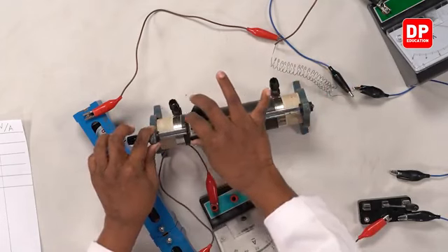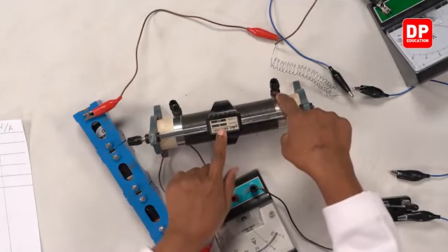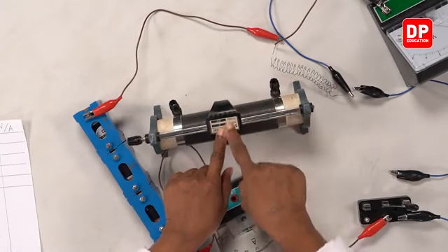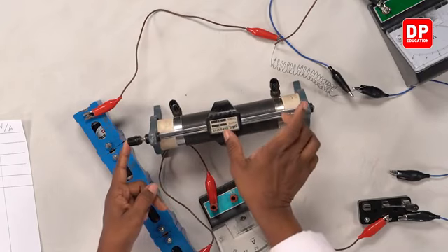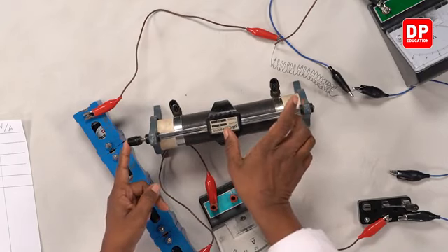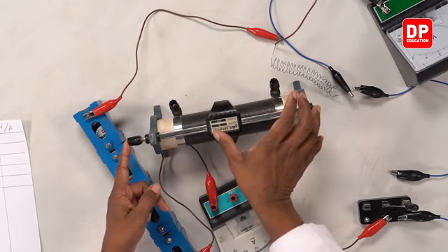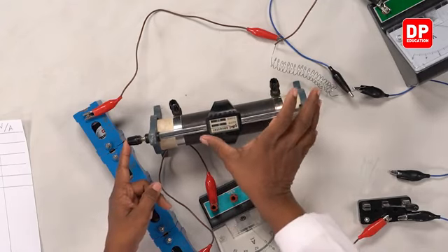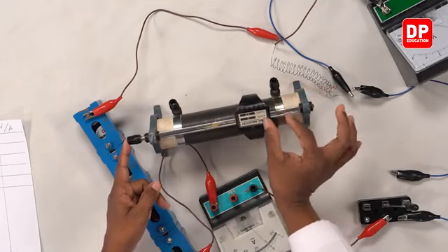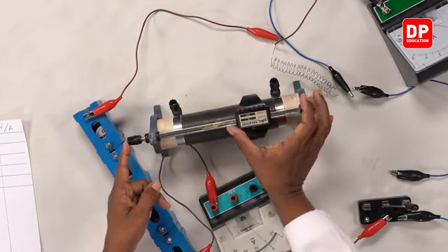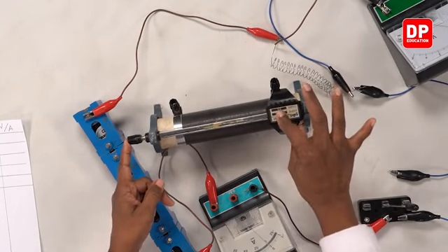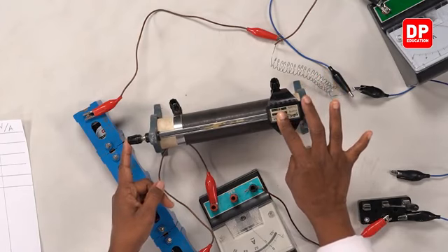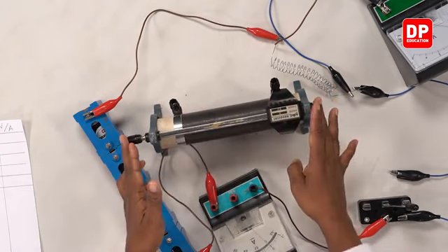If I move it to this side, now from here to here is the nichrome coil, then that is in contact with the rod, and here that is in contact with the knob. So this part of the nichrome coil will give you the resistance. So now what I am doing is I am decreasing the resistance. If I push it further here, only this part, the resistance decreases. When I bring it to this point, no resistance or the minimum resistance is there. That is how we change the resistance using this variable resistor, that is a rheostat.